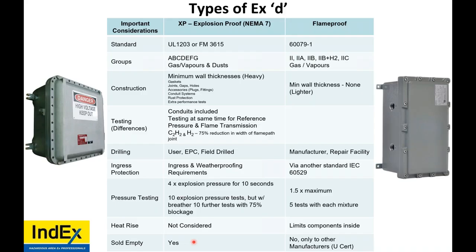Now, can you sell an empty enclosure? Can you receive an empty enclosure as an EPC? Well, for explosion-proof, you can. For flameproof, you cannot. Only if you're a manufacturer, you're planning on putting your own devices in there and then having the box independently certified. So, explosion-proof and flameproof, the only thing they have in common is they're both called EXD. All the other considerations, there are so many differences.